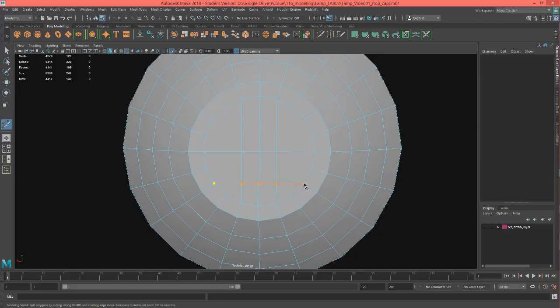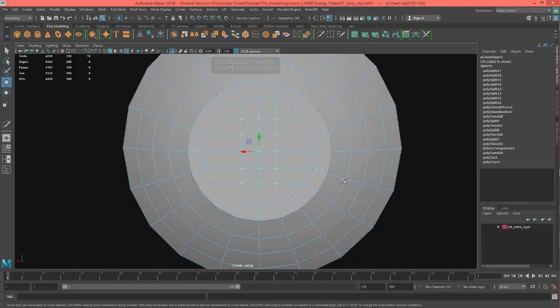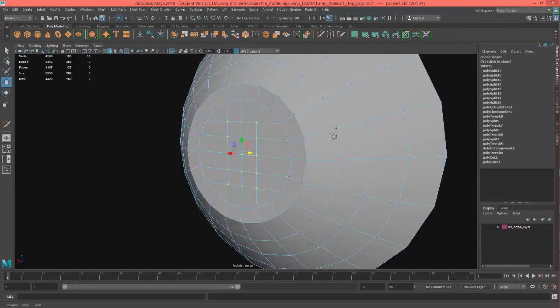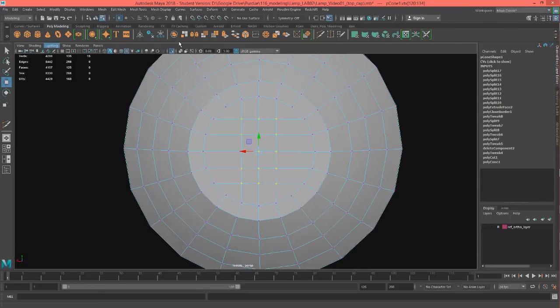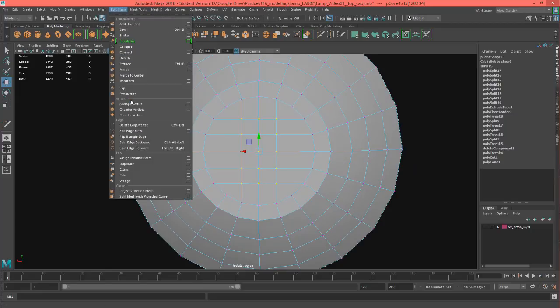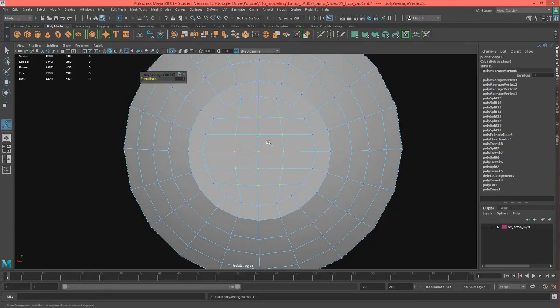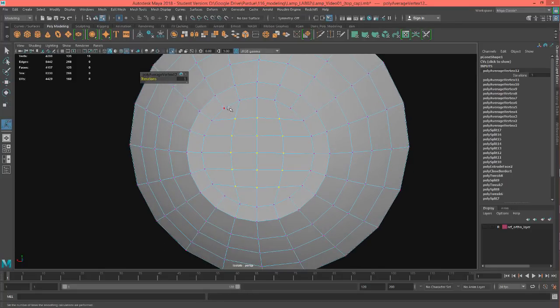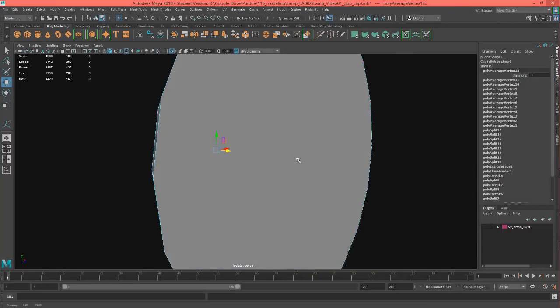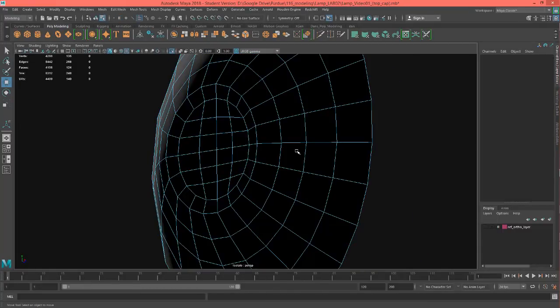And we could pick this one to be where our quad is. So let's see here, like so. Okay, so now we would go to these here, and we'll probably have one selected here. Oh, nope, there's none in the middle there, so we don't have to worry about that. So average verts right there, and I'll hit G a few times and just average those out. There we go. Now, actually this face I don't want, so I'm going to delete that.